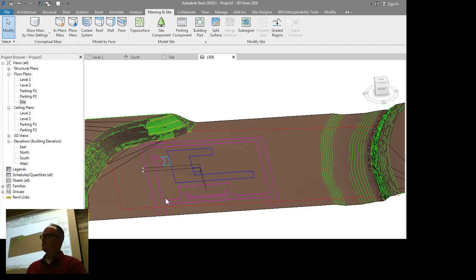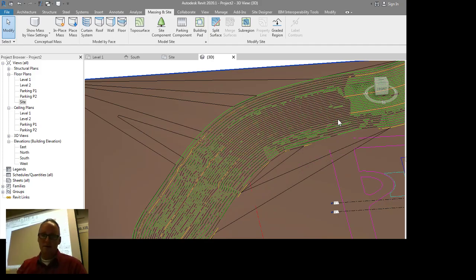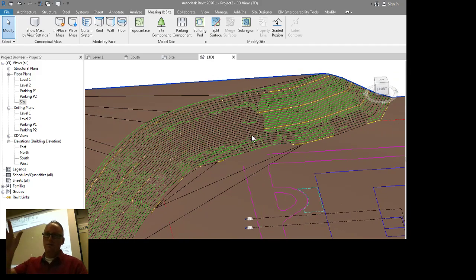Well, after you strip all those points, does that mean the contour gets even more rough? Yes, that's right. So what this does is it makes the resulting surface of the model perhaps a little bit rougher. So if you have more points, it does make for a smoother model of the topography, but that doesn't mean more accurate, right? Because those are interpolated polylines, so they're not truly accurate to the undulations of the site anyway.